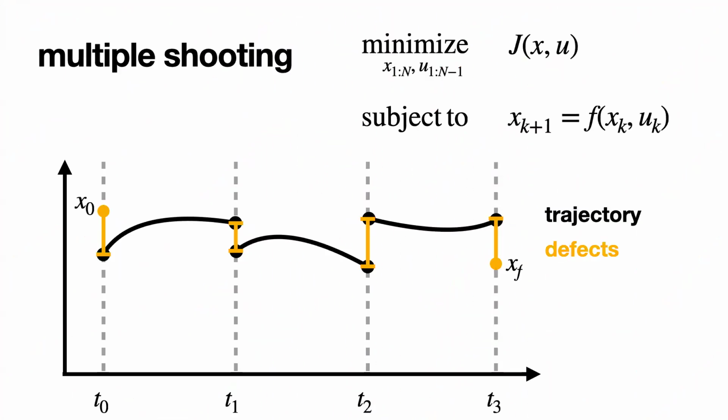So if I was doing single shooting, that means that each rollout is running on a relatively slow GPU single-threaded sim. But if I think about this in terms of multiple shooting, I can be a little more clever. In multiple shooting, what I'm reasoning about is a bunch of different windows of the trajectory, and then I glue them together with these defects. So I'm going to solve a problem that represents the trajectory in a bunch of these windows, and they must actually connect at convergence to reassemble into a real, dynamically feasible solution.